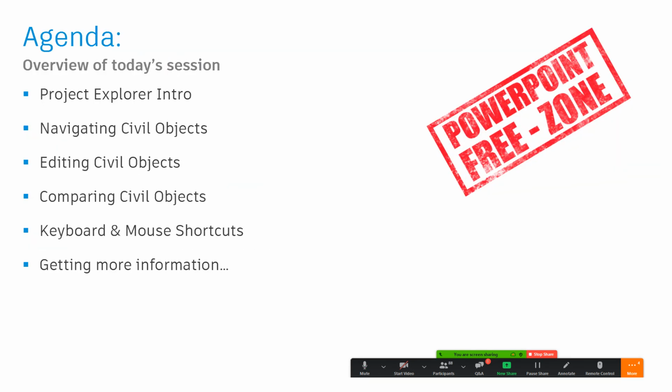Okay, I am going to jump back here. So today, our goal was just to get in, talk about Project Explorer. We looked at that. We looked at how to find it. We looked at how to bring it up. We saw how we can navigate our civil data. We looked at how we can make changes to the civil data, both individual objects and multiple.